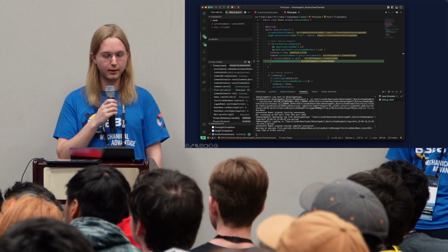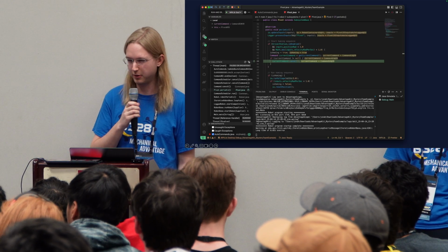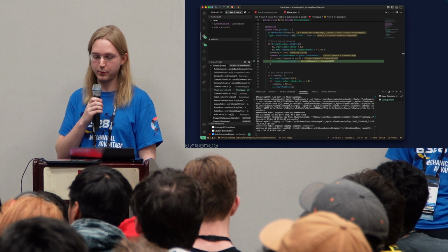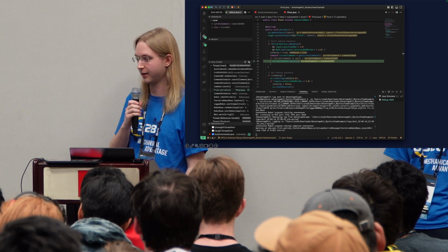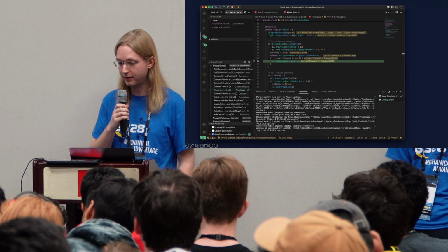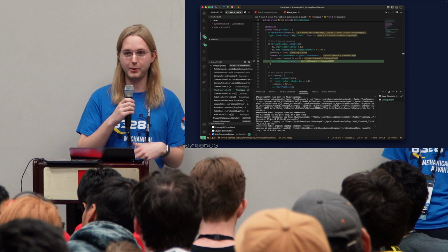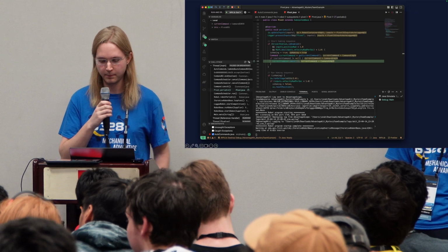And as it turns out, this subsystem included some complex logic for homing its position. So under certain conditions, it would enter a homing mode. And one of the steps before entering that mode is canceling any commands that are running on the subsystem. Since our auto routine requires all of the subsystems on the robot, the result is that we cancel the entire routine, which was probably not what this team expected.